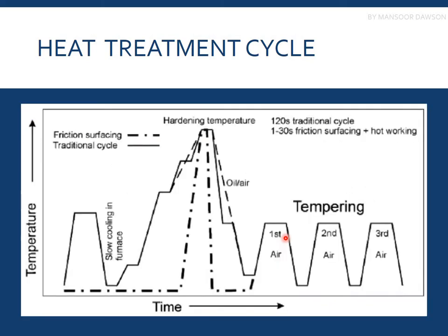Again, this is the heat treatment cycle for only one alloy, or metal. We have heated the alloy to a certain temperature, then suddenly cooled it down at a very fast rate, and then we are heating it at certain intervals. We are providing certain soaking temperatures so that the inclusions present must be homogenized, and the structure is also rearranging while we are holding it at this temperature.